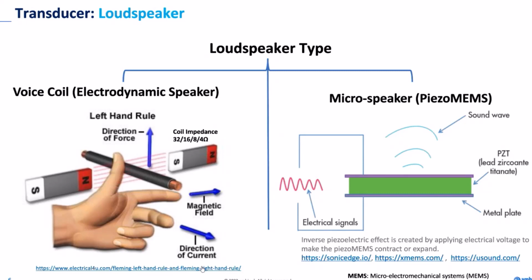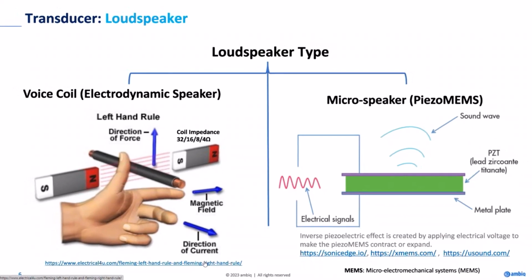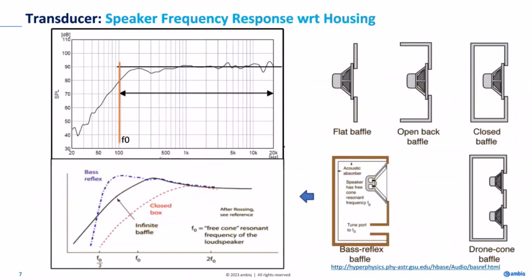They are very linear, specifically Sonic Edge, which uses basically an ultrasonic pump, and they claim that you can automatically boost at low frequencies and also at high frequencies. And when we talk about the equal loudness curve, or which frequencies are responsible for loudness and intelligibility, it turns out that the MEMS speaker has greater potential in terms of cost, performance and power consumption.